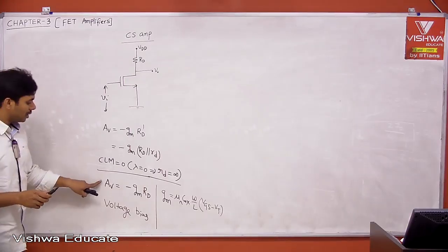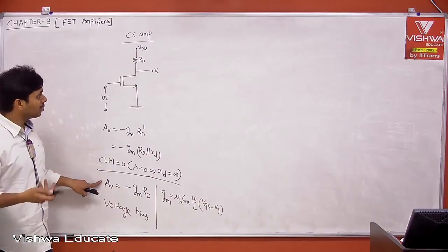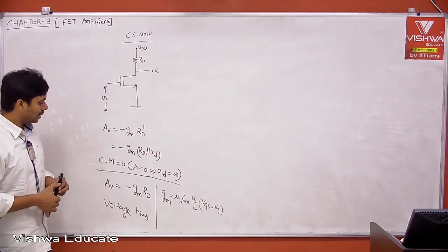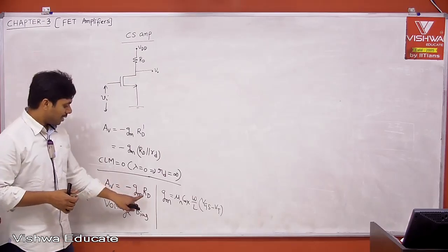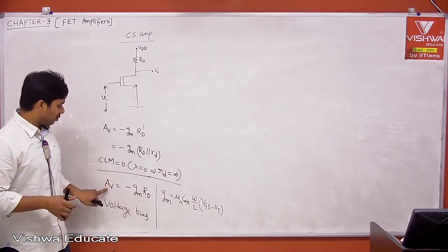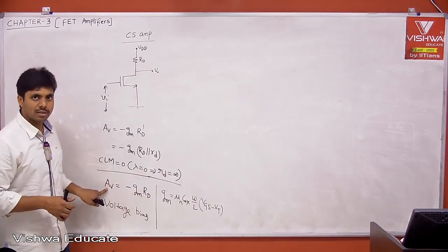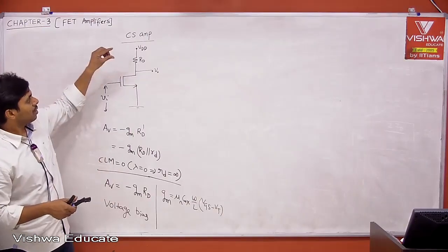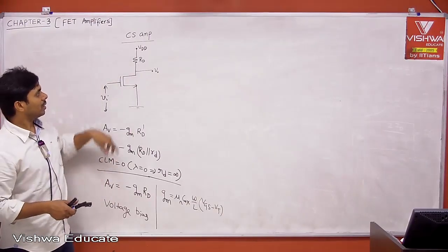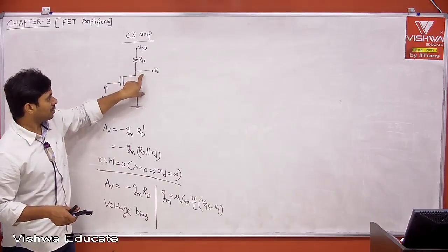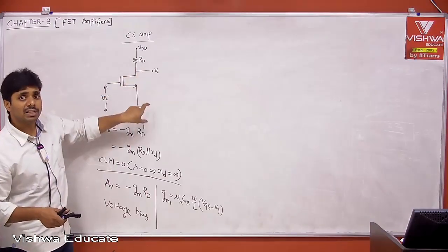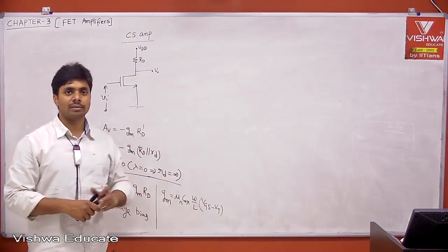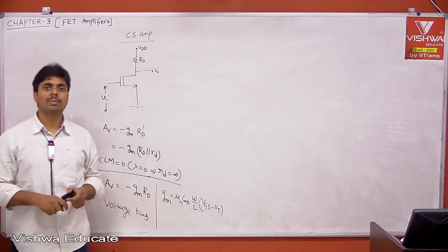But I want to increase the voltage gain. I am thinking from an improvement point of view. If I want to increase my voltage gain, just mathematically, tell me, if I increase my RD, can I increase my voltage gain? Yes. But remember, from an AC perspective, if you increase RD, the VDS you are getting will decrease, then it may enter the linear region, and then it will not act as an amplifier.